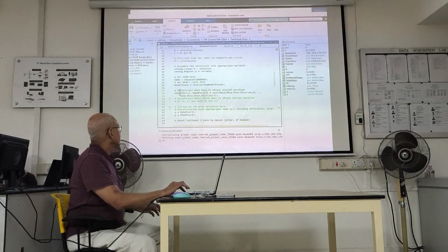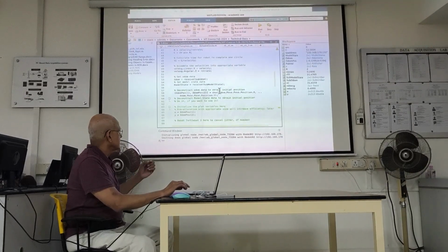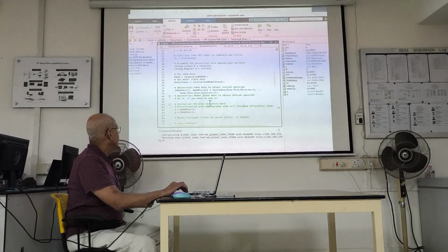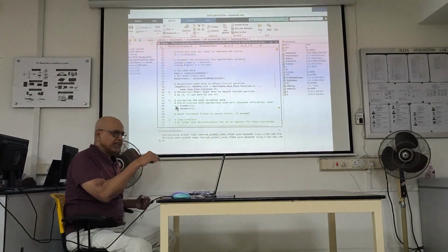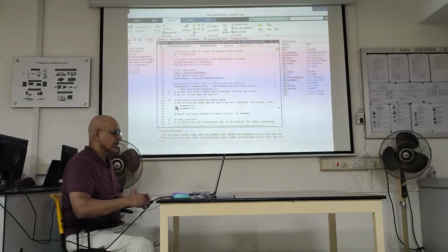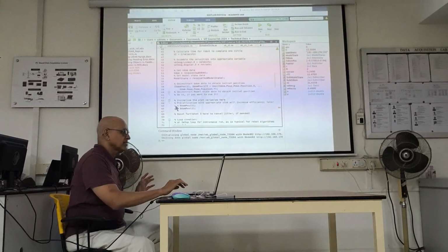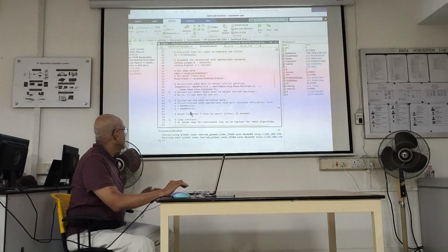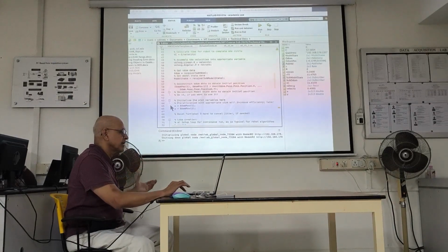So the initial odometry values, X and Y, I unpack, and then I initialize my plot variable. So I'm going to keep on adding to this. It's going to become an array shortly. The next point will make it an array and then it will keep on growing. This is not the best way. MATLAB doesn't like it because it slows down the computer. But visually, or to understand the program, this is a better way of doing it.